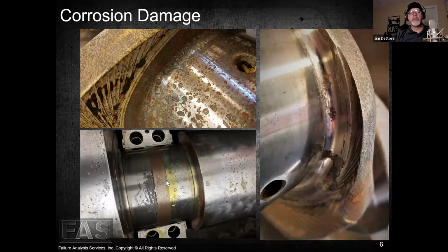And on this one here, this aerial crankshaft, we had water in this frame as well. So this bottom picture with the corrosion of this aerial crankshaft, we had water intrusion into the frame along with lubricant being present. What we tend to see with the water corrosion is pits, like we do in this crankshaft picture to the right. When we have water mixed with the lubricant, it tends to leave a very dark or black surface. The industry term for this is black acid etching. This is what lets me know that this thing sat for a while. There was water present in the oil and it corroded this area here. And notice how dark and black it is, Michael.